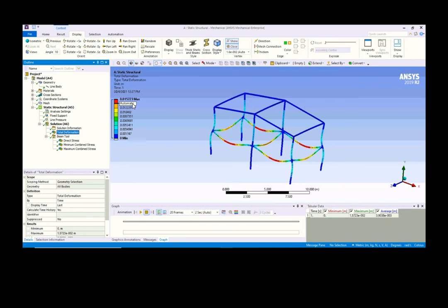If you are using a very small mesh size, then probably you will get more accurate results. But is it needed for this so-called simple problem or not? You will compromise on your computational time, so you have to give and take.